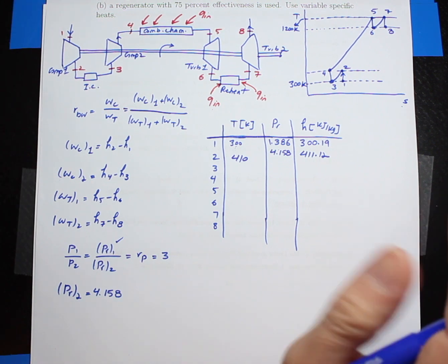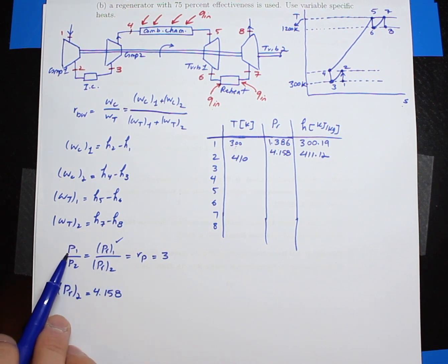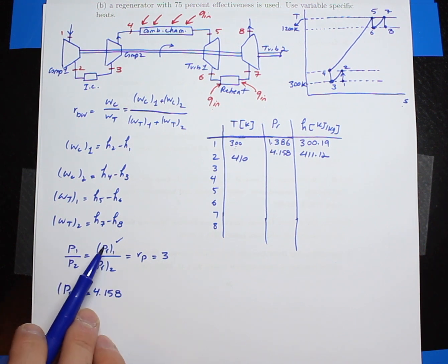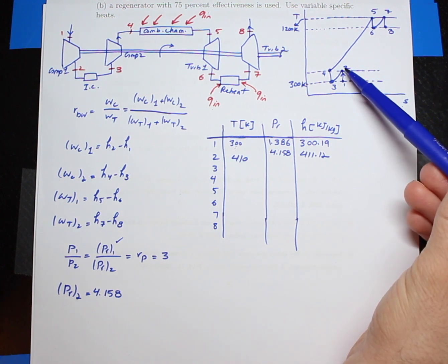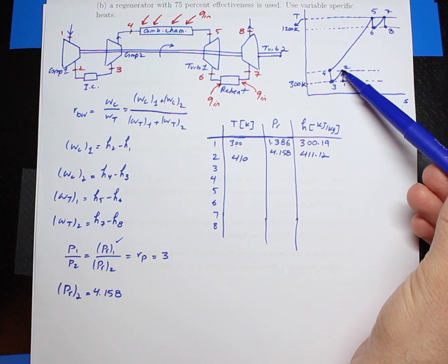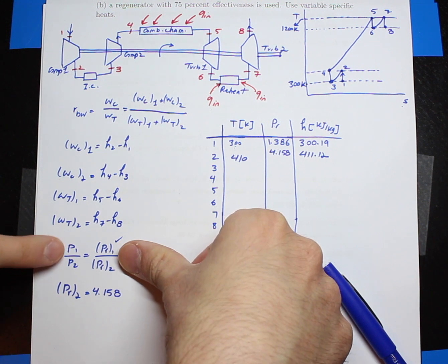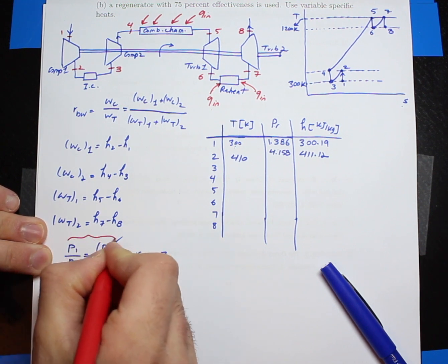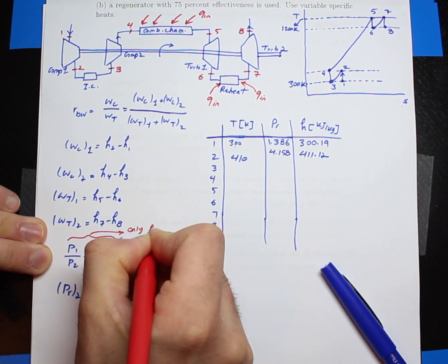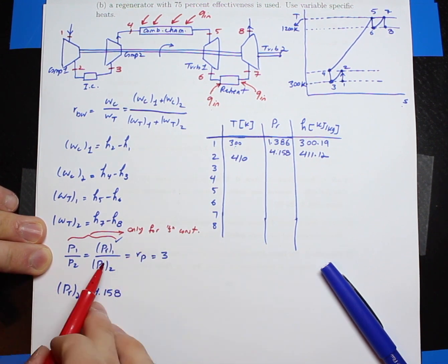All right, so before I continue, let me explain one thing. You want to be careful with this equation. This is only good for S constant properties. You can write the pressure ratios based on the relative pressure ratios as long as your entropy is constant. If your process from 1 to 2 is not an S constant process, you cannot use this equation, the equation of the pressure ratios. So this portion is only good for S, or entropy, constant. As long as your entropy remains constant, you can do the same thing here.